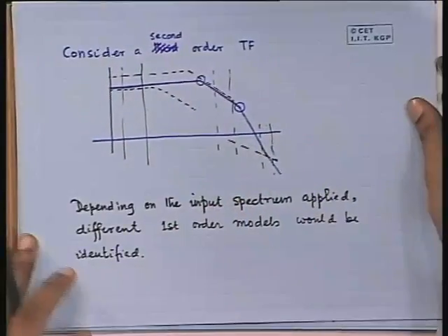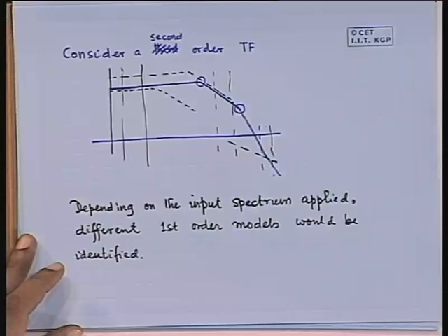So you can find a good idea of the order by looking at the data matrix properties. That's what I'm trying to get at. By taking the matrix phi and computing either a determinant ratio or identifying the singular values of that matrix, you can get a very good idea of what is the likely order. So we are coming close to the end.